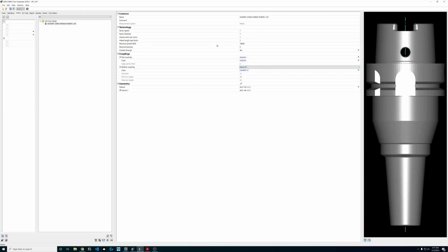We did glance over, you can set a maximum feed rate. The reality is that we're not meeting the maximum feed rate of these machines. You can also put in, you see these are all one-to-one factors for speed, feed, and depth and width of cut. If you're using a particularly long holder, or if you're getting into stuff with angled heads or anything like that, you know that we're only able to use a portion of the tool's feed and speed data, and those can just be defined really simply here as 50% of whatever it was programmed at. Okay, we'll hop onto our last tab for today, NC tools.